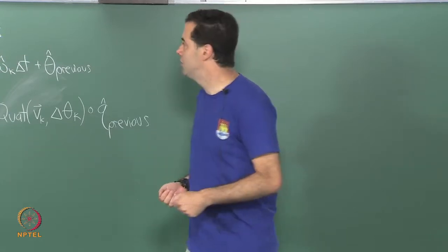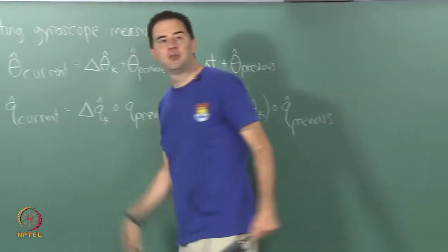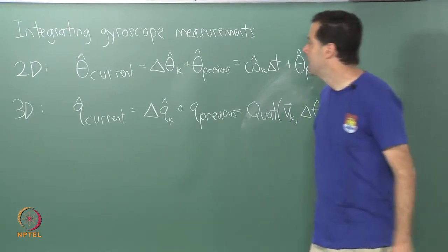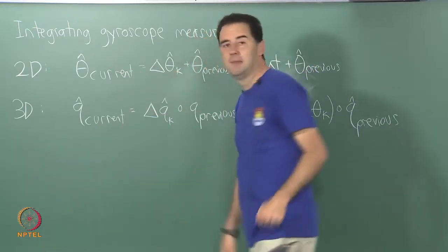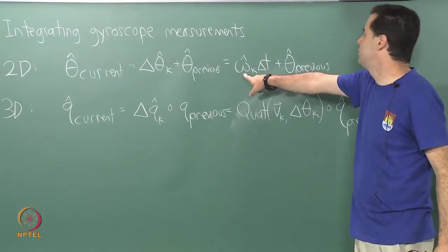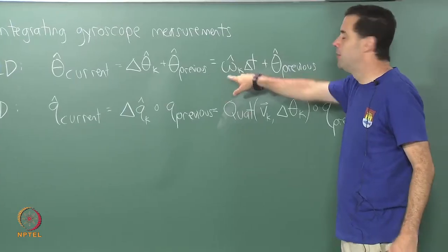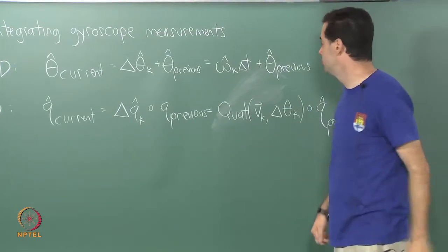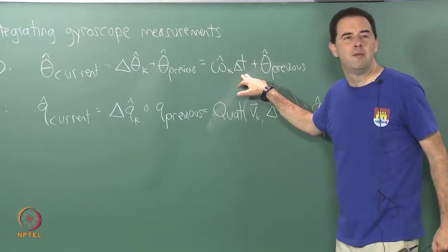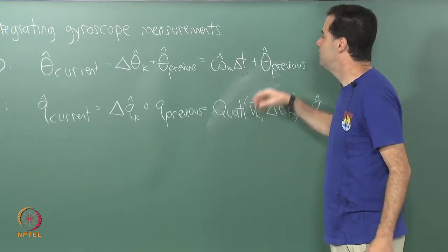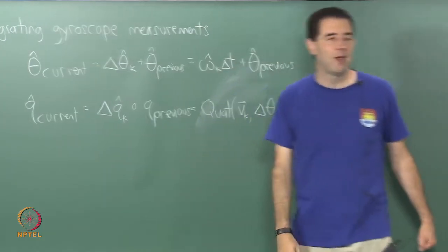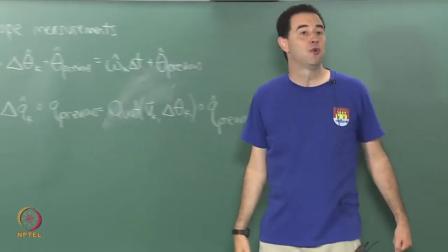We got into the case of integrating gyroscope measurements, which provide readings in terms of angular velocity, so radians per second. In the two-dimensional case, I gave a simple example, imagining a merry-go-round or a top spinning. The measurements are just scalars, essentially rotation with respect to the vertical z-axis. So you have omega k hat at each step, and delta t, which is 1 millisecond for our examples. We have this very simple update: we calculate some change in theta estimate and just start adding, in each step, and keep repeating this equation over and over again.